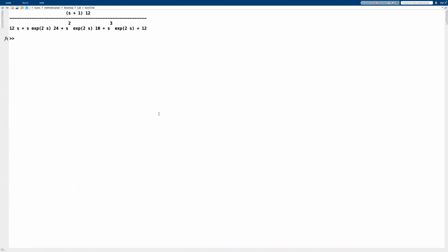And there we go. This is basically the result of our calculation. Now, you can see that some terms in the denominator will have e to the power of 2s in them, and some will not. And it's obvious why we will have this, because of ns plus ns times the numerator of the controller, which is s plus 1, plus s times ds. And then, of course, ns has this exponential term here.